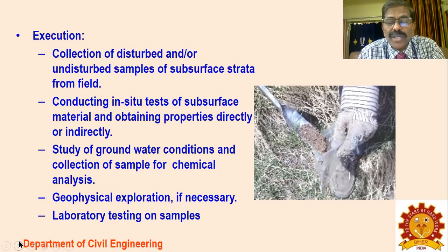If the samples are collected undisturbed, then you can get the real site condition values of the soil bearing capacities, soil penetration test capacity, and so on. You can put that sample into your triaxial test to find the angle of internal friction phi, and similarly you can get the cohesion from the triaxial test or the UCC test, things like that. If the soil gets disturbed, such tests may not be possible.